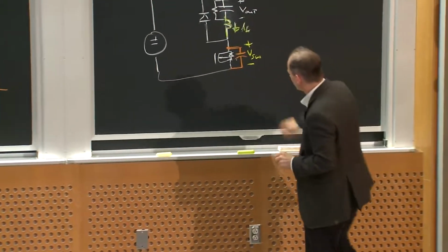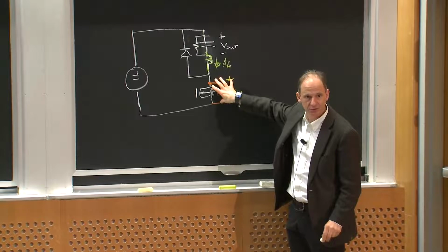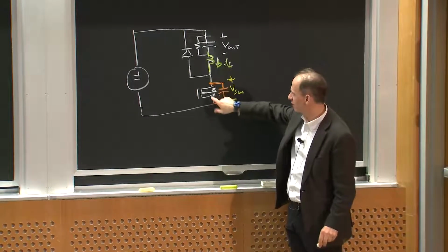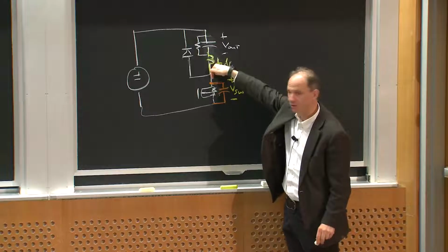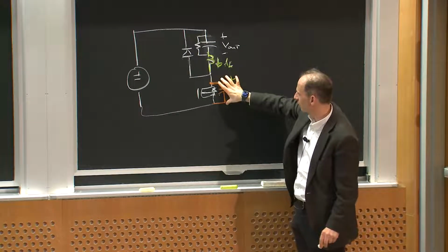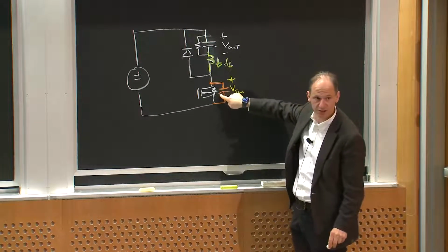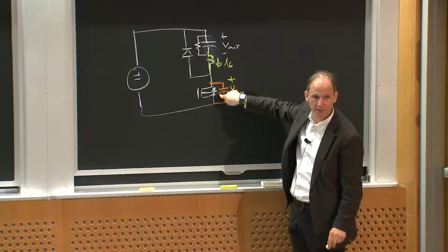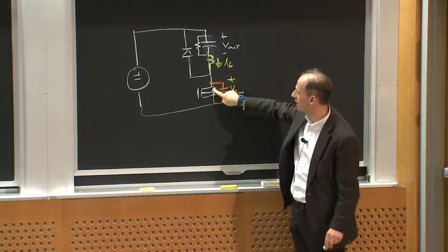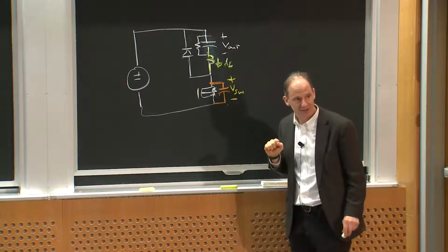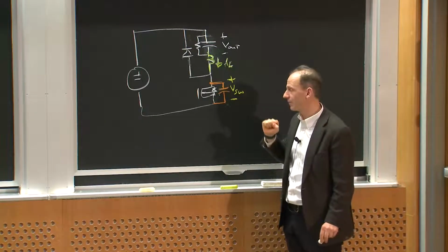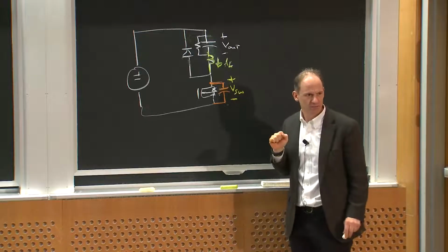All devices have some internal parasitic capacitance, right? So even if I turn this switch on with zero current coming from here, if it has voltage across it, I still dissipate energy in this switch, right? So if I want to think about the energy associated with the switch capacitance, I really need zero voltage switching.